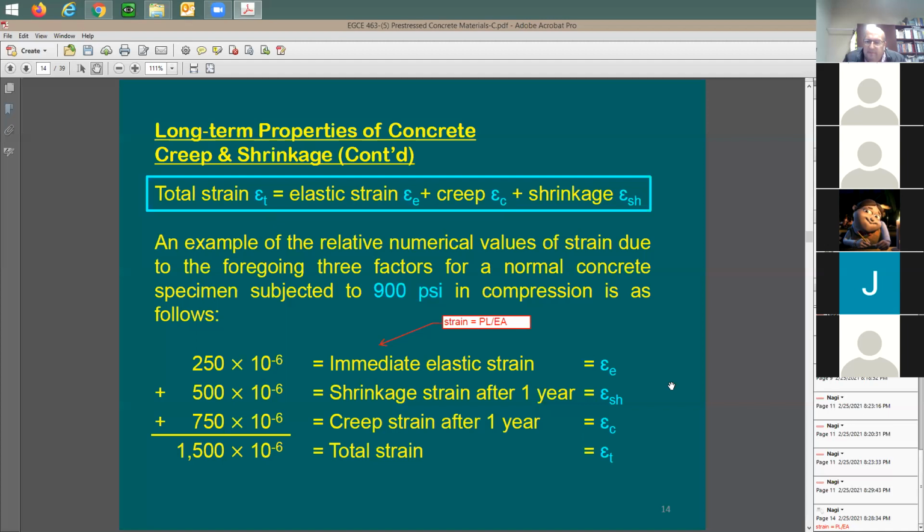Also, you're going to be concerned if you go more than 4 feet for a lift. This is what the code says, maximum 4 feet for the lift. So once you start to pump the grout, you can just explode the bottom block, which is too bad. You don't want to do this, right? So what people tend to do is secure the bottom 2 blocks, put some shoring or bracing there. You put some pieces of wood and try to brace it.